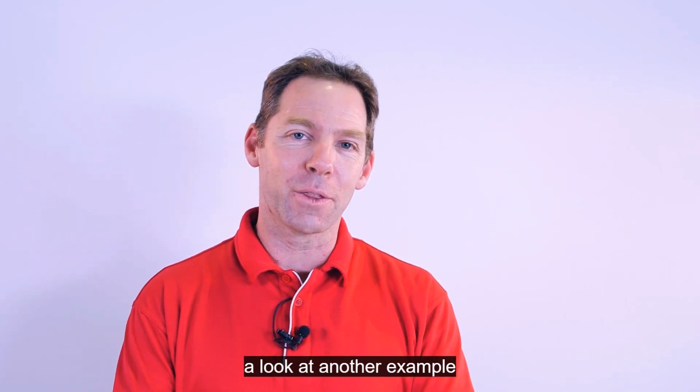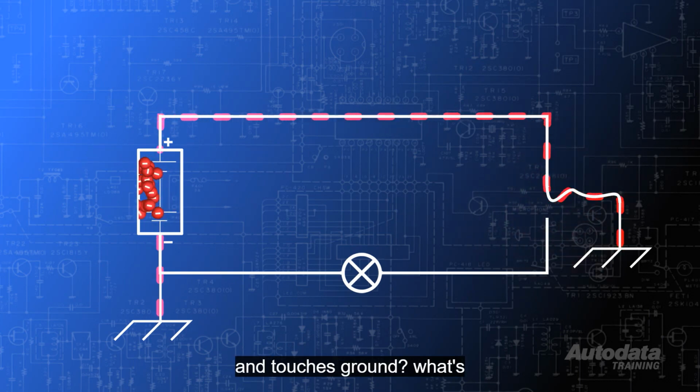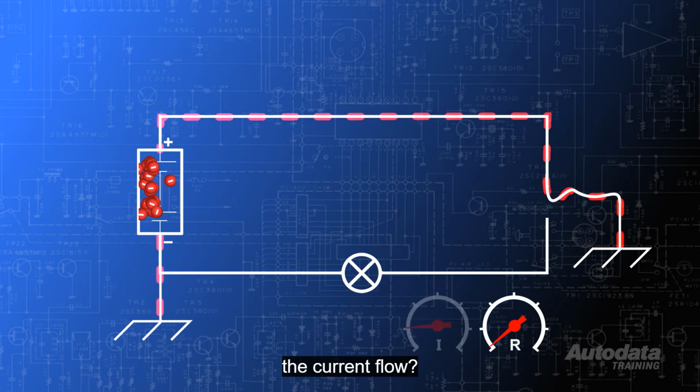Let's take a look at another example. What if the wire from the battery to the load breaks before the load and touches ground? What's the circuit resistance now? Zero, right? So what happens to the current flow? It keeps rising until the wire burns through, or the fuse blows.